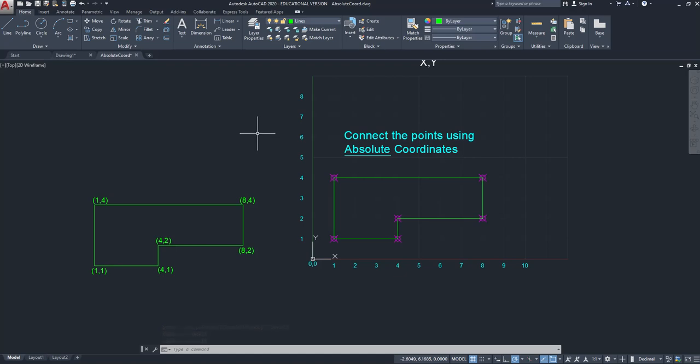Yep. My computer's been doing kind of weird, like after I type in the command, the next command I put in is relative to that point. I'm trying to figure out how to turn that setting off. Do you have your dynamic input turned on? It's turned off, but whenever I make a line, it still has the angles on it. Yeah, I think you're relative. Let's see, go click on that again. That's just the button, so then you turn the button off. Oh. I think that's what's happening. Yeah, dynamic input will interfere. It kind of just picks the best method, if that makes sense.